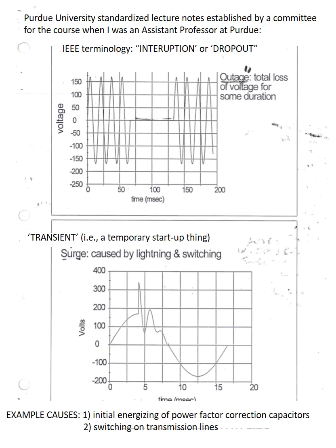Hire a professional electrical engineer to do your power thing, especially if you need a bank of capacitors in your factory to cancel out the power factor problems because of the inductance of your motors, which you get penalized for, by the way, from the power company in the rate that they charge you. So that's for another lecture.